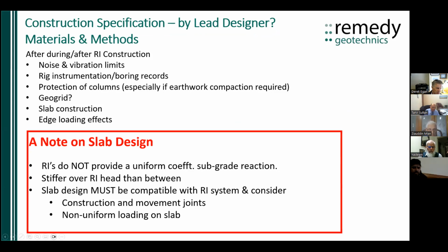If you're doing a rotary displacement, you should be able to get, or ensuring that you're getting, some sort of computer readout of penetration, torque, crowd force, and definitely the placement of the concrete in the ground. That is a really important quality control check. And obviously the length of the columns, to make sure that they are terminating in ground that is suitably strong to support them.